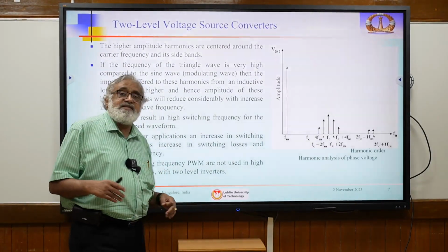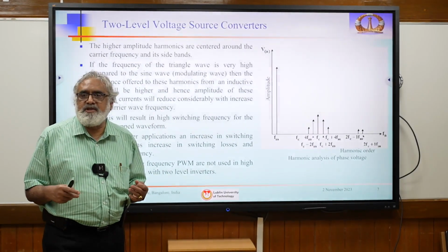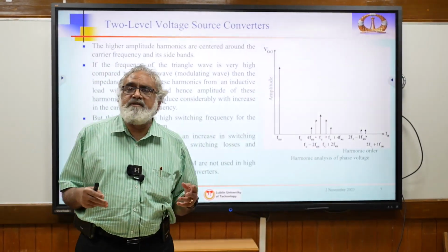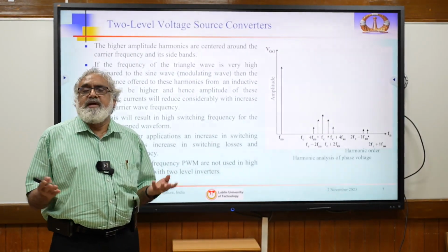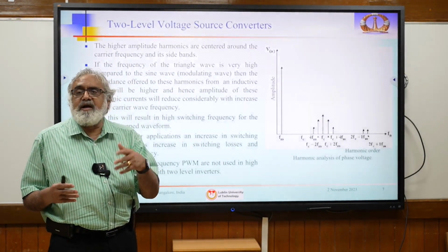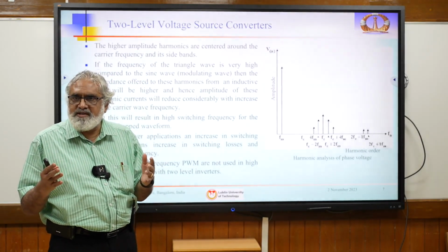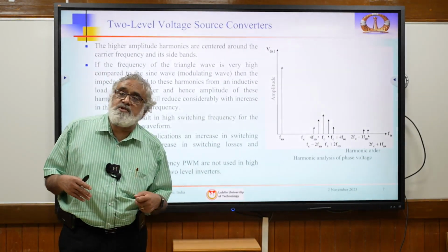But the problem is how much high frequency we can use, especially for high power application, medium voltage drives application. We cannot go for very high frequency. Probably for low power SMPS we can go for high switching frequencies of kilohertz and megahertz. But for high power application, this is not possible.